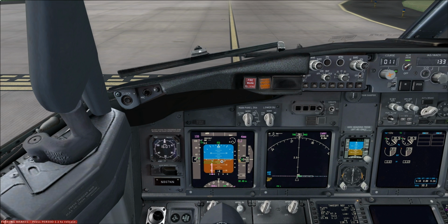It also says if you get a go-around windshear ahead aural alert, you perform a windshear escape maneuver, or at pilot's discretion perform a normal go-around. And of course you monitor your instruments carefully.